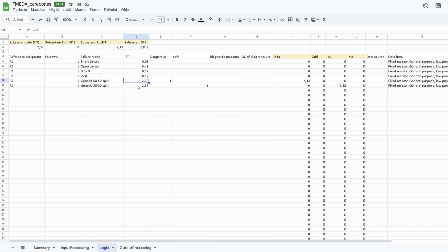And now the pessimistic thing I was talking about can be viewed from the failures that this military standard produces. We can see that the failure rates estimated are more than 5 to 10 times higher than for the data gathered from Exida. Keep this in mind while doing your analysis, because garbage in leads to garbage out. But, of course, too pessimistic leads to you being very pessimistic with your approach and designing in very much margin.